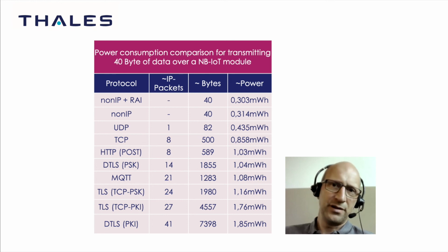The mobile operator will offer their customers different ways to access this data. Maybe they push the data to an internet server, or they offer a kind of web GUI where you can pull the data. But this push and pull doesn't affect your power consumption anymore, because this is on the network side, and so this is really the best solution from a power consumption point of view for the device. But of course, the MNO offers this as a service, and you might have to pay something for this service to get a non-IP data connection.